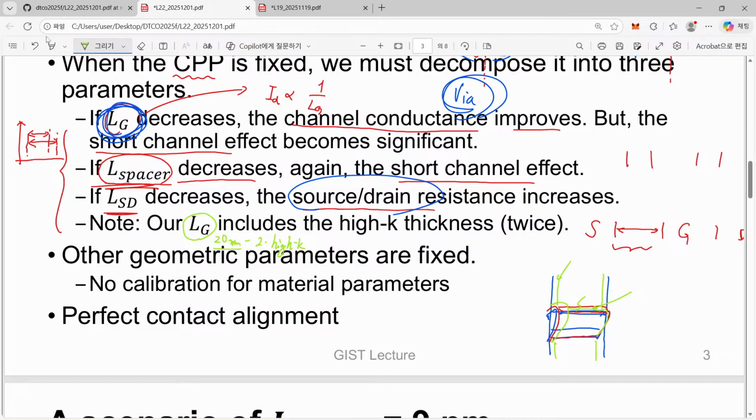In our example we have made a quite inaccurate assumption, like all of our dielectric layer is just 1 nanometer thick pure silicon dioxide. In reality our high K layer thickness is not 1 nanometer, it is about 2 nowadays, and previously it was about 3 nanometer.